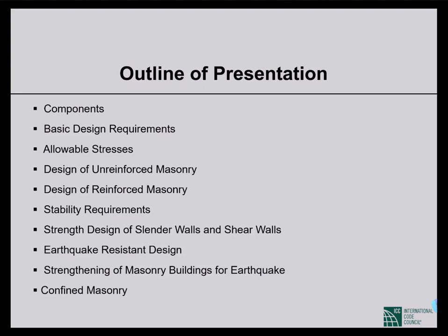The allowable drift is quite large in the case of frame construction compared to unreinforced masonry. So it is very difficult to proportion the stiffnesses properly between framing and unreinforced masonry construction.